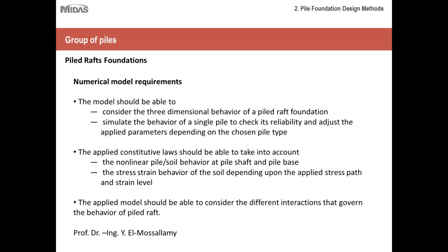So now that we understand that numerical analysis is the way to go, we have to find out what the requirements are from your numerical analysis model. As you can see here, the model should be able to consider the three-dimensional behavior of the pile raft foundation.